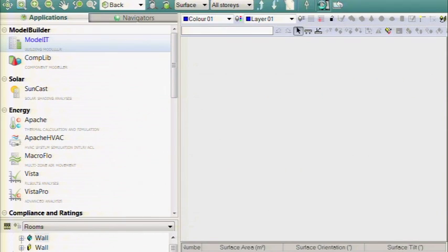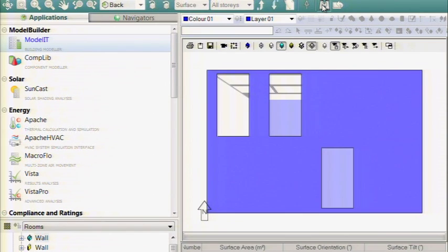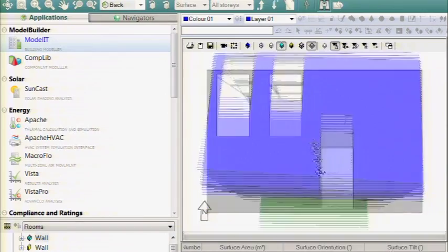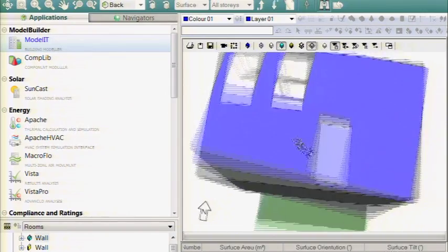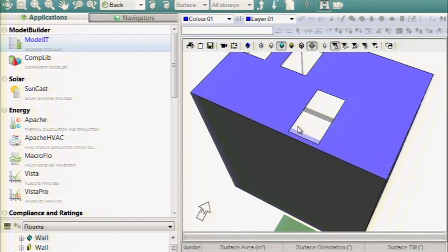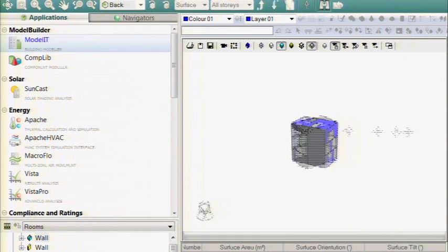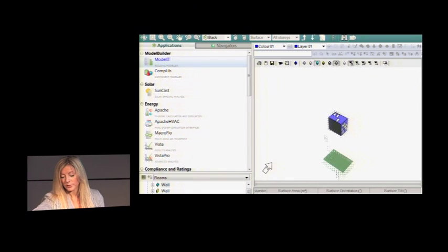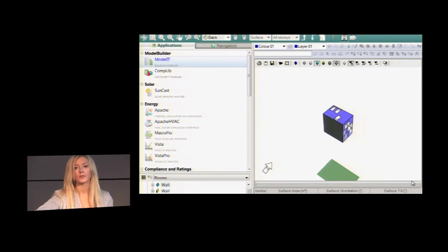Half the time you'll see that the model is actually floating 250 feet above the ground plane. So make sure that it is actually set on the actual ground. In this case, you can see a perfect example of that, where it's above the ground, because they put in the actual elevation for it. So that needs to be moved back down.